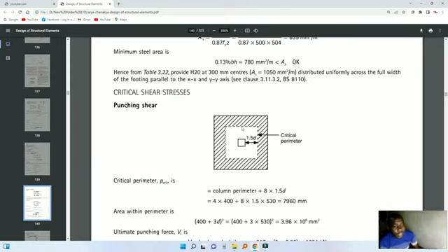Then we've got the D, which is this side, that side, that side, and that side. Okay, which are the depth of the column, or the side of the column, which are about 400 according to the column size that we had in our calculation. It is based on that information that we use this formula. Critical column perimeter, this is the column perimeter, times 8 times D times 1.4. Now we come up with the perimeter here.